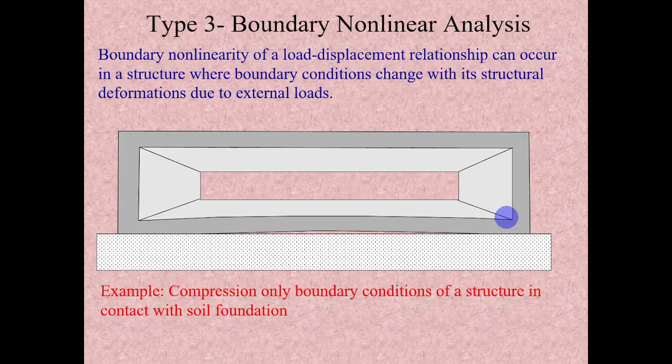The third is the boundary nonlinear analysis. The boundary nonlinear load-displacement relationship can occur in a structure where the boundary condition changes with the structural deformation due to the external load. For example, a compression-only spring is used in a structure in contact with the soil. A foundation is one example of a boundary nonlinear analysis case. In this case,